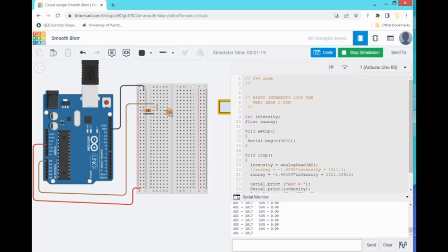For example, if you are measuring illumination, it would be great to have this value read against illumination. So you have a relationship between resistance and amount of illumination to get that right. And then you will discover if this photoresistor is linear or not. So far, I assume for this calculation that it's linear.